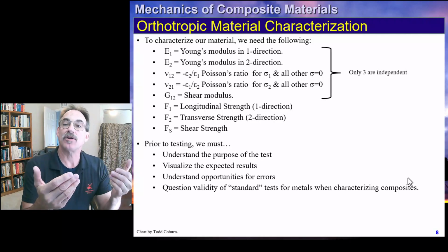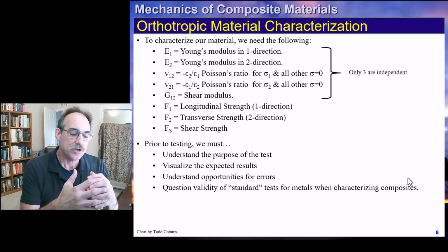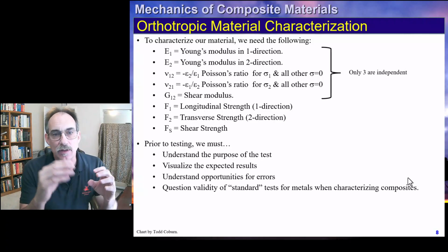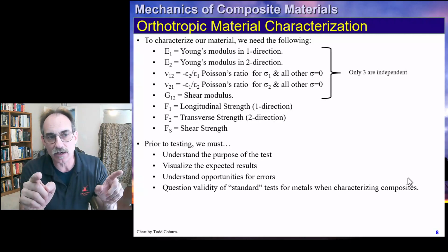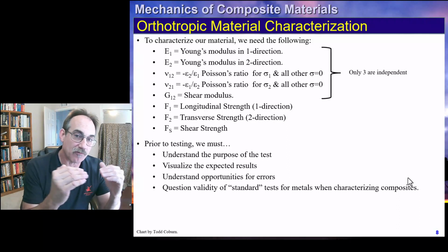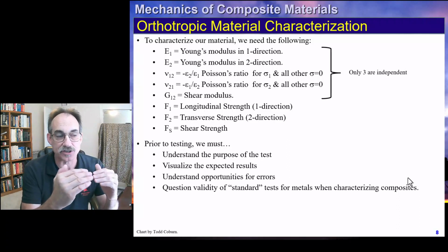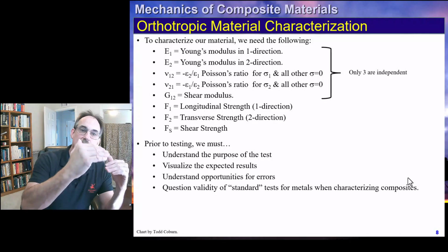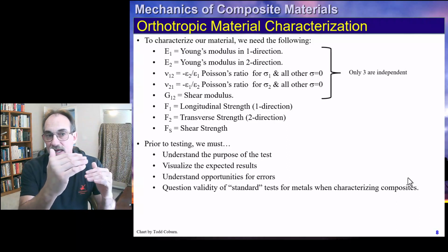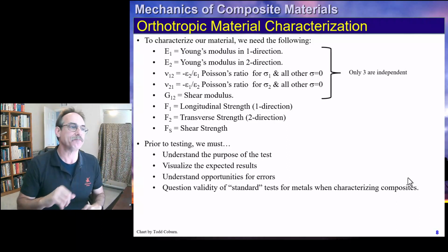You may need to characterize all of these, or with clever engineering, you may be able to bracket these and say, well, I'm going to test this, this, and this, which should be critical. These two samples are going to tell me not only what the allowables are for a certain thickness, but the allowables for another thickness, and use analysis to show that because we have characterized it like this and analyzed between that, we may be able to quantify other ones in between.